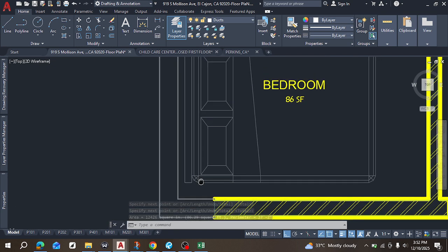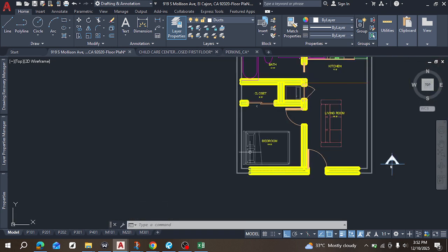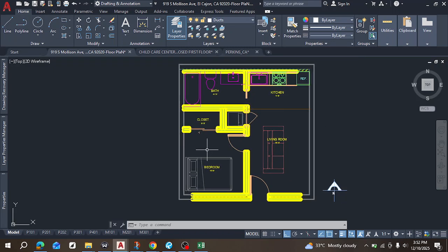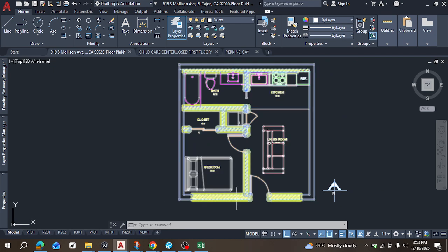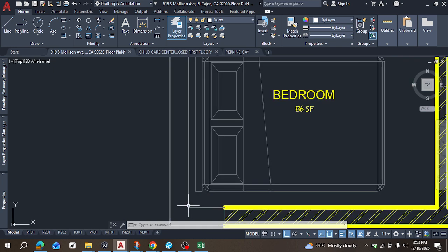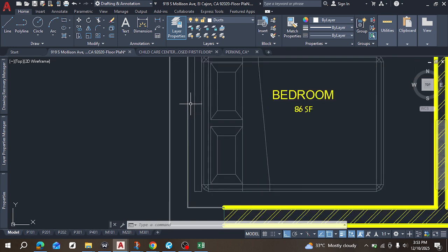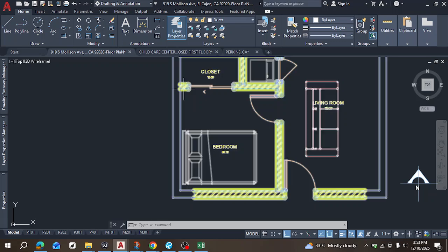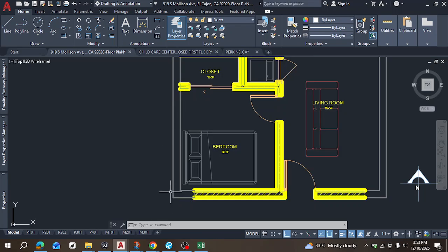So yes, why it didn't match is because we are taking the walls into consideration also, right? This interior wall starts from here and ends here. But when you look at it from the exterior wall, all the heat that enters this room is actually taken off from this actual distance of the external wall. So that's how we use the external wall length instead.